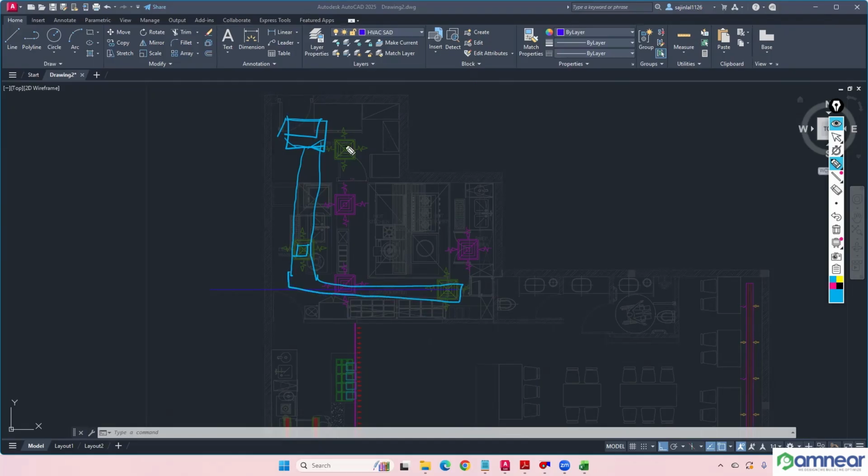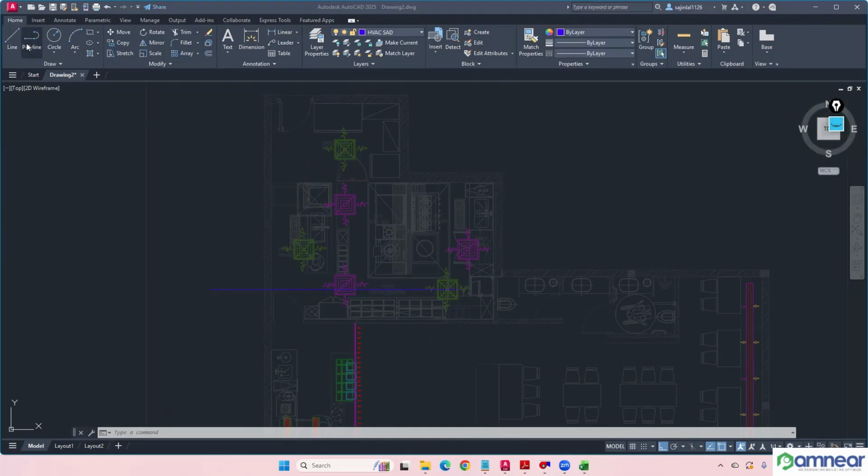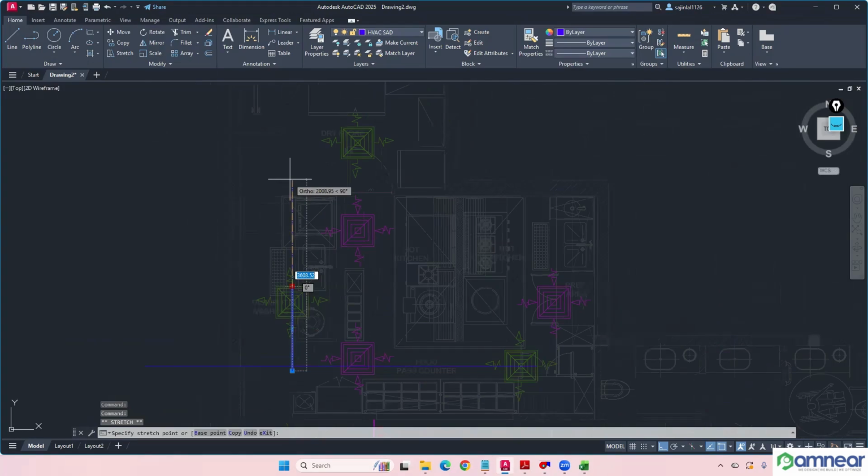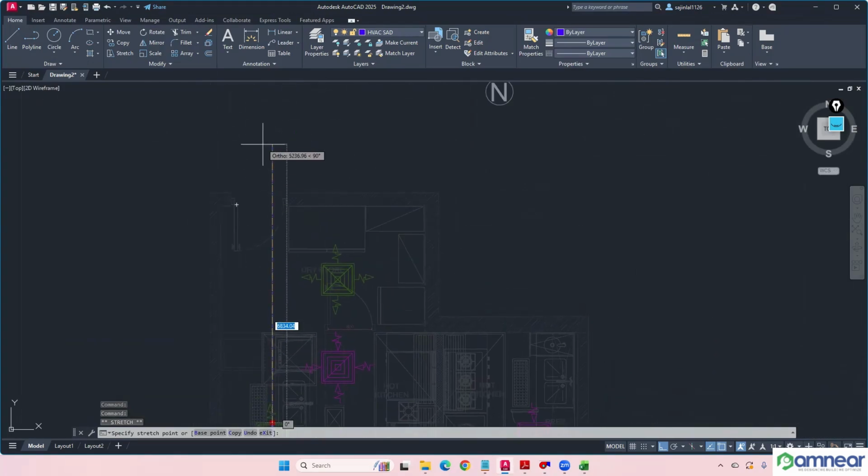Anyhow, taking a route will be difficult. A rigid connection will be difficult there. So here I'll be going for flexible duct and plenum box. As per the location, like that only we can do. So that's why we need to get the center point, because if you want to take a drop, you should get that center point. To get the center point, I made this. Somewhere there, I need to propose my machine.